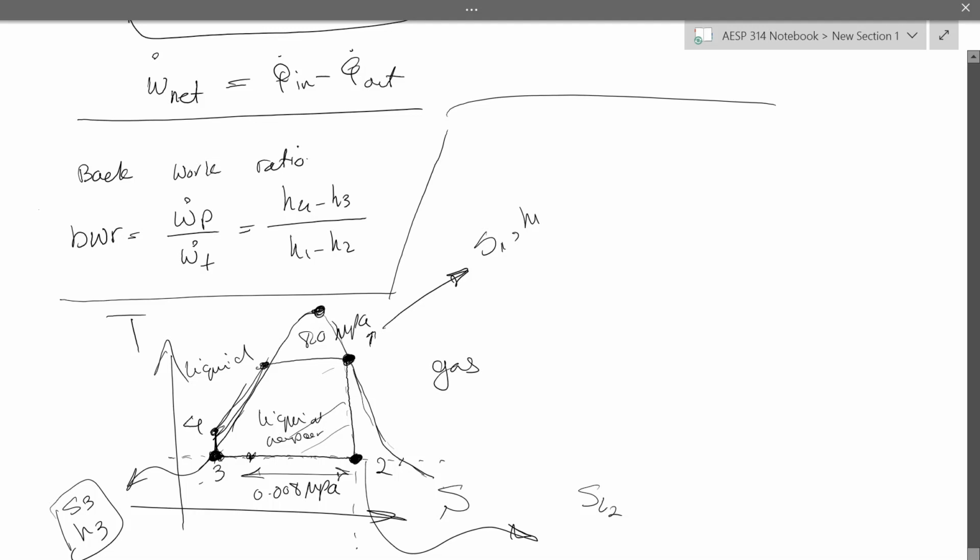Yes? You add that to the entropy of the gas at state 1? No, because you have lost some energy there. The energy level has changed. Temperature is not constant over there. So you can only do that between station 2 and station 3, or this point and station 1. The energy level has to remain constant.